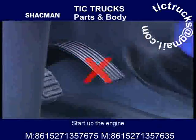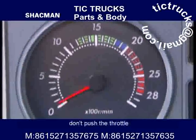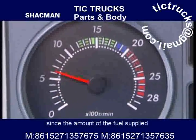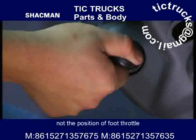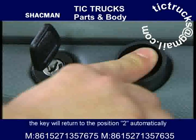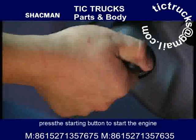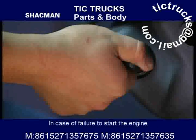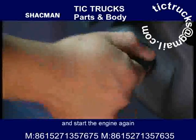Start up the engine. Turn the ignition switch to position 3 to start the engine. Don't push the throttle, since the amount of the fuel supplied while starting is determined by ECU, not position of foot throttle. Release the key after engine is started up. The key will return to the position 2 automatically. For S2000 vehicles, press the starting button to start engine. In case of failure to start the engine, turn the ignition switch to the position 0 and start engine again.